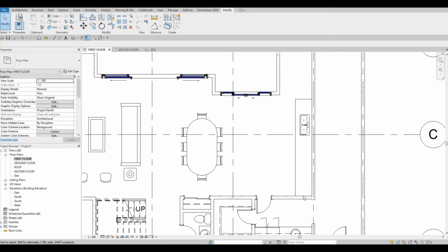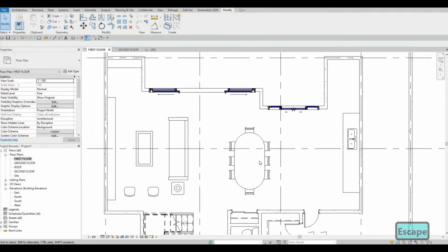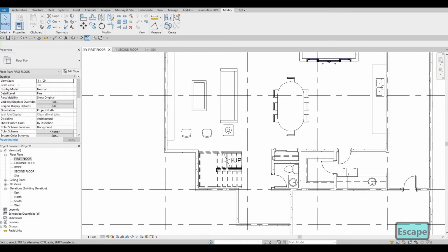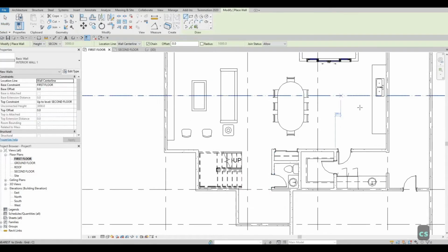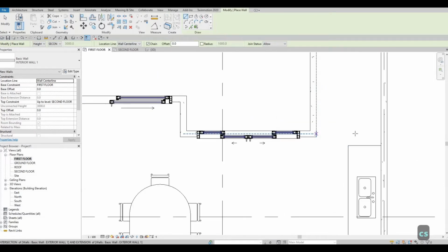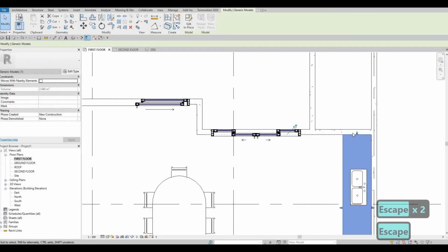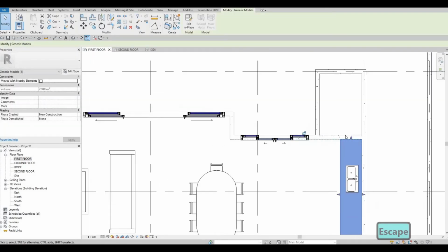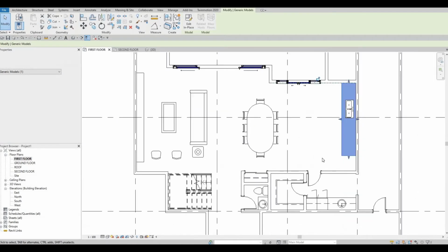So I'm giving it some space now. So spacing. So I'm just gonna pull this one right here, add a wall right there. So that will be interior wall. So I'm gonna select interior, CS, that's create similar, and then I'll put it in the middle right here. So now this is closed off. We can push this back all the way to the wall right there. And then after that, we can add in a door.